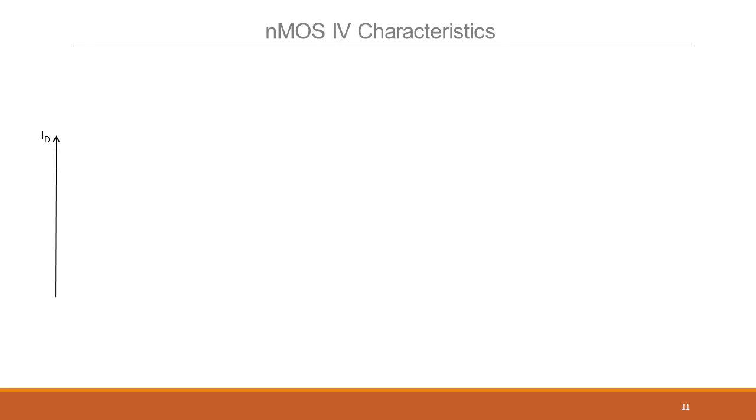So let's draw the MOS characteristics. Okay. ID versus VDS. Let's say first we go above the threshold. We know below the threshold there's no current, and let's say we go 500 millivolts above. These are all old geometry transistors, so let's say 500 millivolts above. In the newer ones, you might have to do with 50 millivolts or even 10 millivolts, depending on the supply ranges. Right? So initially for small VDS, the current is linear, right? And then it tends to reduce in slope as VDS increases a little bit.